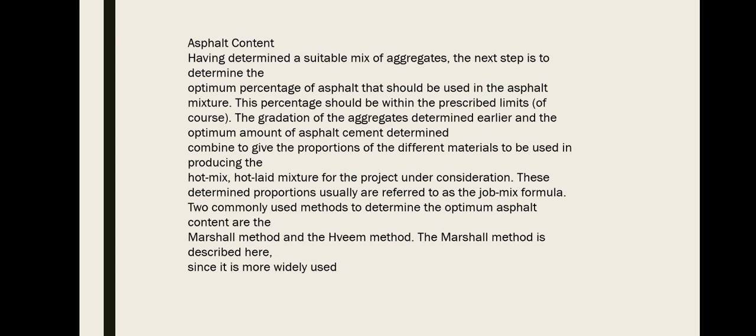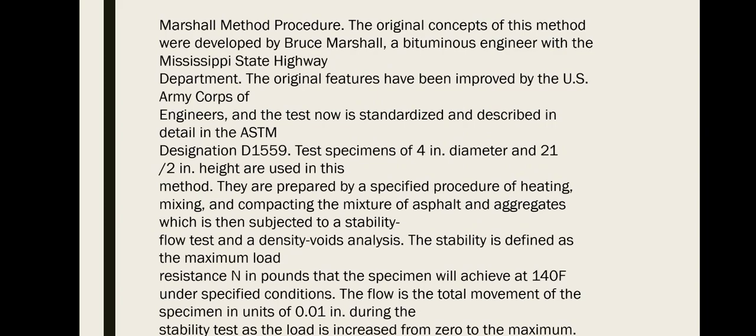Two commonly used methods to determine the optimum asphalt content are the Marshall method and the Hveem method. The Marshall method is described here since it is more widely used. Marshall method procedure. The original concept of this method was developed by Bruce Marshall, a bituminous engineer with the Mississippi State Highway Department. The original features have been improved by the U.S. Army Corps of Engineers. The test is now standardized and described in detail in ASTM.